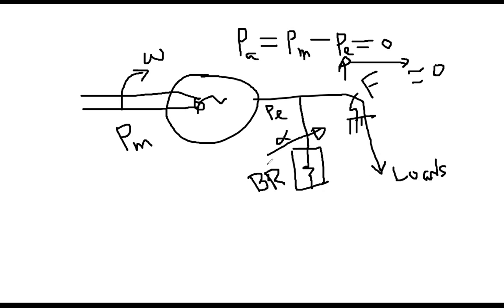Each time you send the alpha to the thyristor, your power consumption through the braking resistor is changing. Through the switch, you are continuously changing your Pe. Sometimes 100 megawatt, sometimes 98 megawatt, 90 megawatt, because you are controlling the current flow by controlling the alpha value, and that is happening at millisecond or microsecond rate.